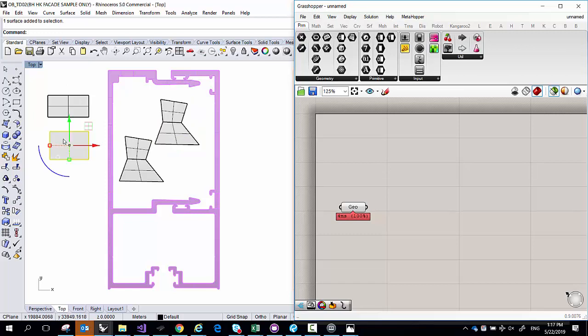Now you've created here two surfaces. That's not, data-wise, the exact same thing as what we want to play with. So what I would do if I were you is delete this. You can copy one of them, because what we want is for two of them to converge to one polysurface. And to do that, the easiest thing is to join them, right? So if I just say join, and go up here, it tells me what it just did.